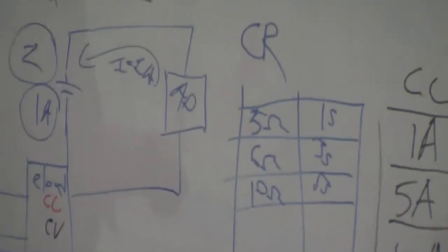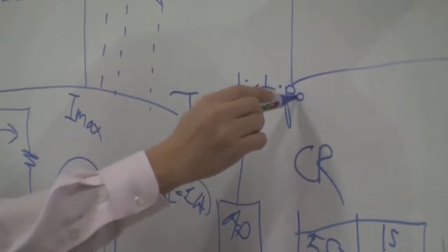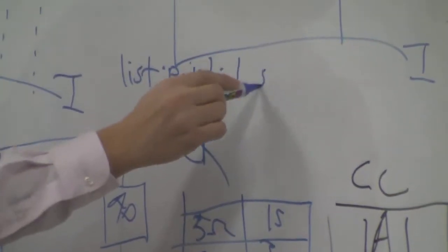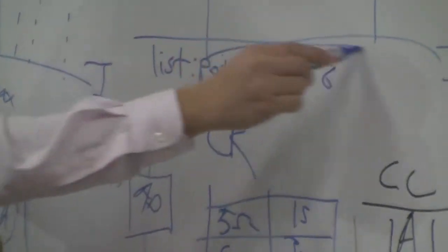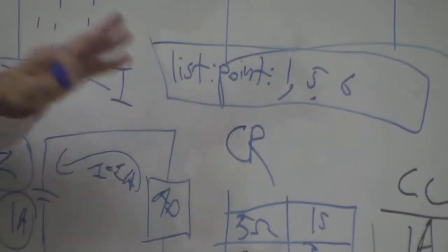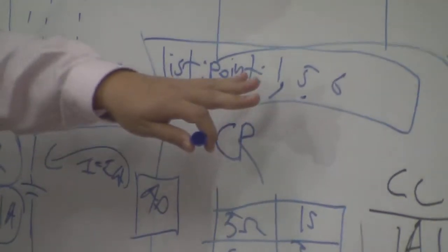No, you don't need a program. You can download the Agilent IO Libraries. It's free software, a free program, and it works with commands. So the command is going to be like list point. Then you start going 1, 5, 6, the resistance that you want. So it's probably just 3 or 4 commands to set this up. But you punch in the commands and